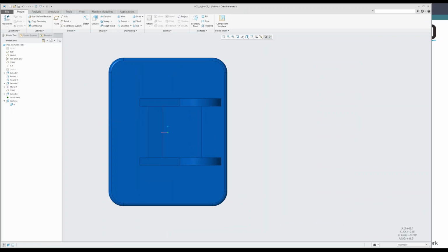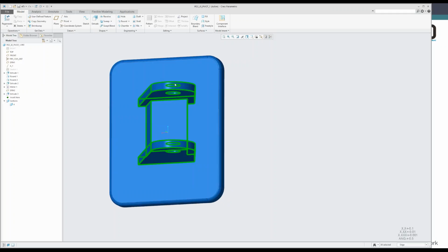Now this next item I actually really thought was fantastic. It's really simple, but it's now built into Creo 4, and it's really going to save a lot of people a lot of time, and that's box select. One of our customers told me that they individually select many surfaces and edges, and it's a big tedious task for them to do. So now it's built in where you can do a box select. Let me change this to edges here. If I left mouse button down and drag a box around this, I'll select all the edges that I went over there. I can go ahead and right click again and add around.